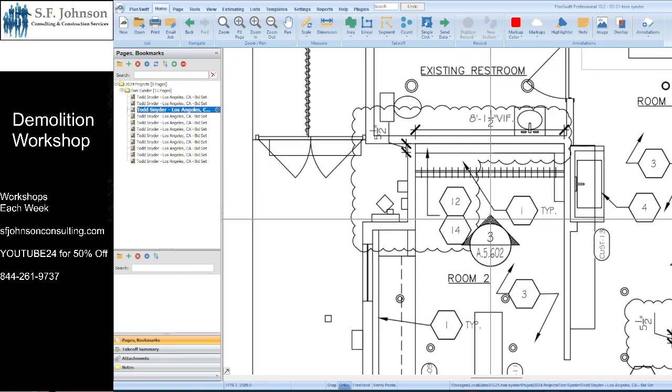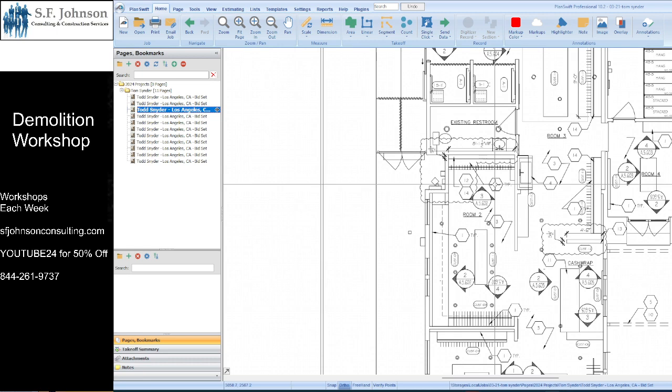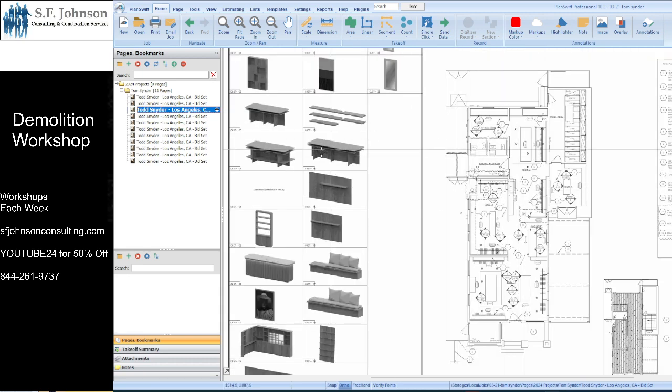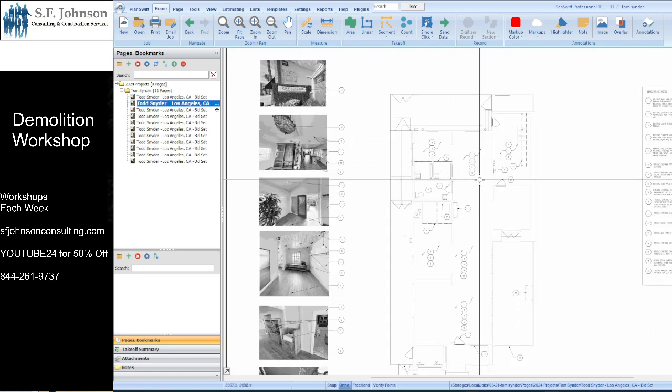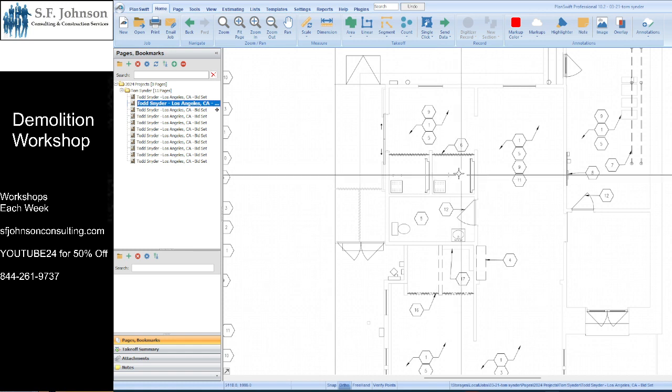You'll receive the man-hour calculator. So whatever the scope of work is, you'll have an Excel spreadsheet where you'll input how many linear feet, square feet, or whatever you're doing, and it'll kick out how many man-hours it should take you based on construction industry standards. So that's what we always want. Okay, so let's go back to the first page, because I said demo. Okay, that this was a demo estimate.